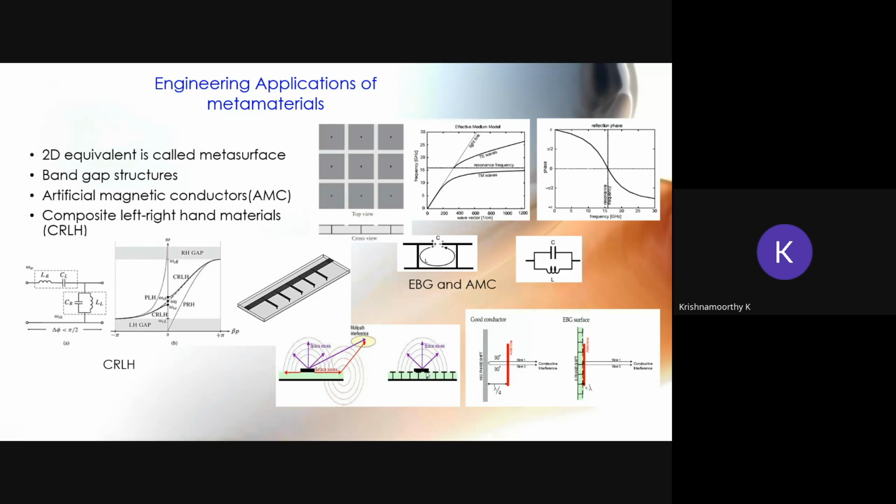so that we can improve the radiation characteristics of the microstrip patch antenna. Here, the side lobes we can reduce. So you see the conventional microstrip patch antenna. We have the finite ground plane, and whenever we have the finite ground plane, we have surface waves. The surface waves propagate and radiate in the unwanted direction, so we have some side lobe effects.